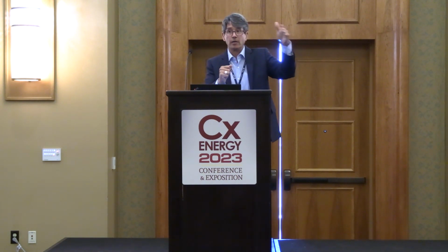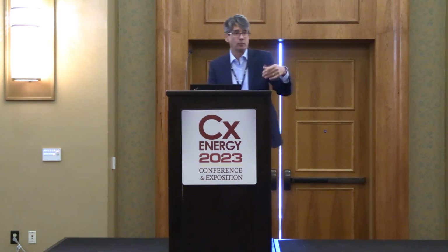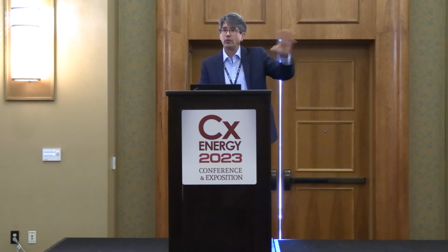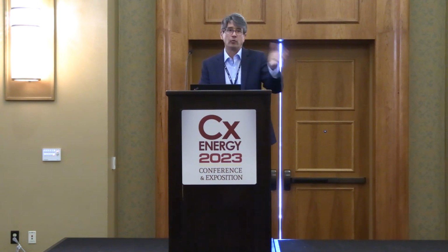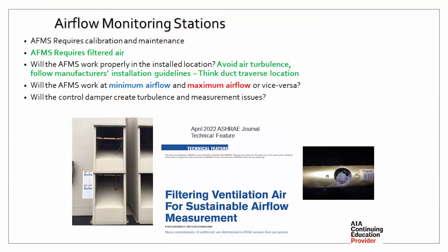Not only for the outdoor air, but they were DX. They were all tripping out on high head. They forgot to put the baffles in between the condenser air and the intake air, so they couldn't figure out what was going on in these things. All of a sudden, somebody asked, who provided the louvers? Well, the architect. Oh, yeah, those are special. And they pulled one off and said, no, that's why. So be careful if that louver selection gets changed from what the manufacturer did.